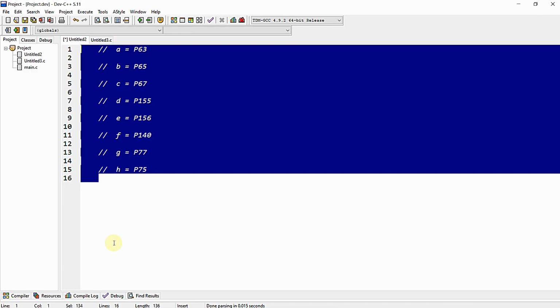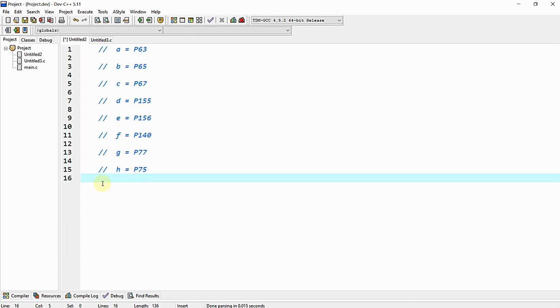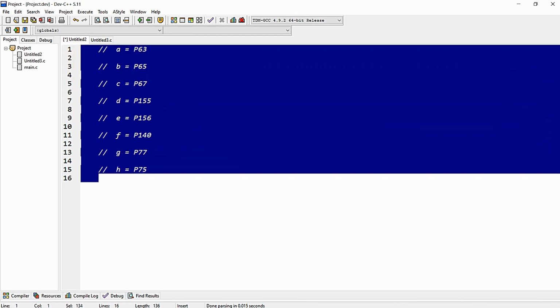As we know, the 7-segment display is an output device and it is nothing but LEDs connected to 8 terminals of the microcontroller. We just want to configure the corresponding pins to which the 7-segment terminals are connected as output pins, and you can manipulate the data shown on the 7-segment display with the help of the configured output pins. So let me configure all these pins as output pins.